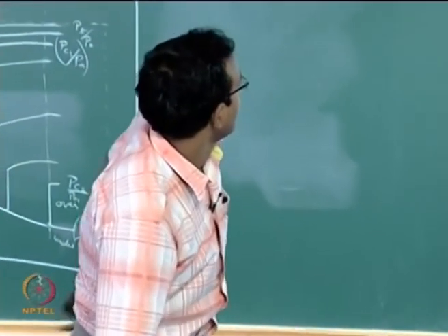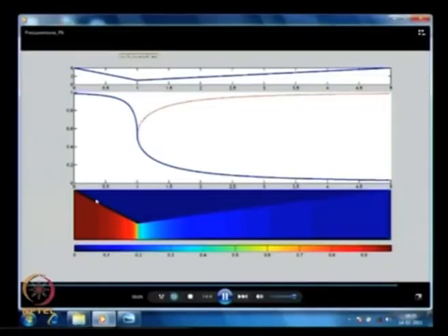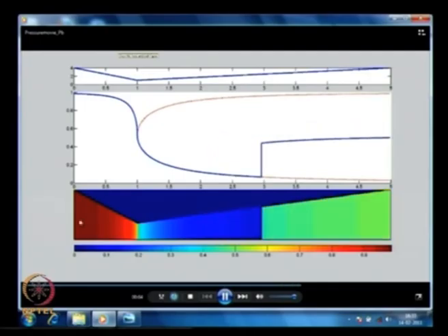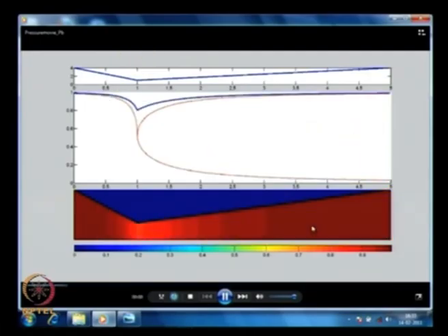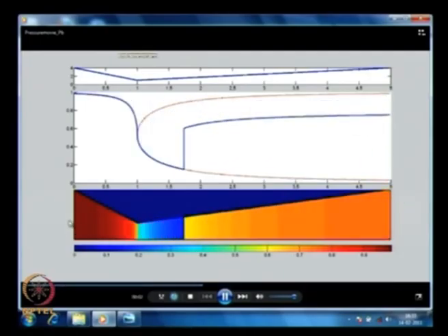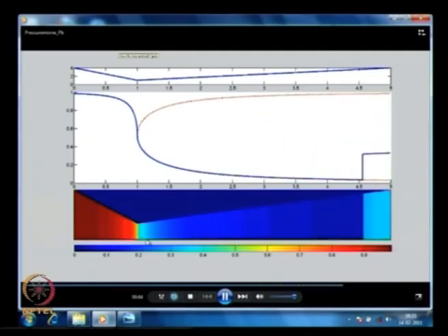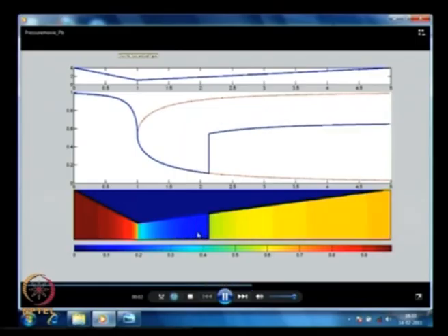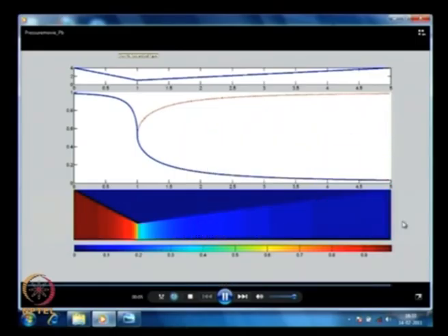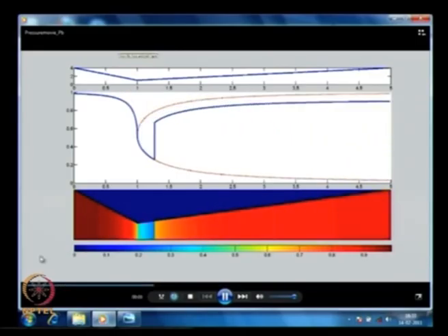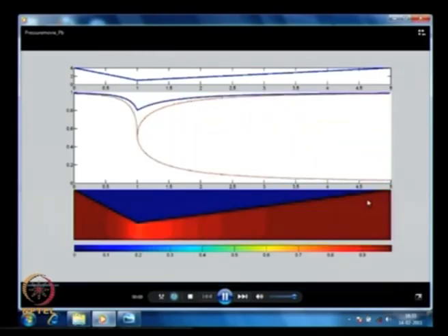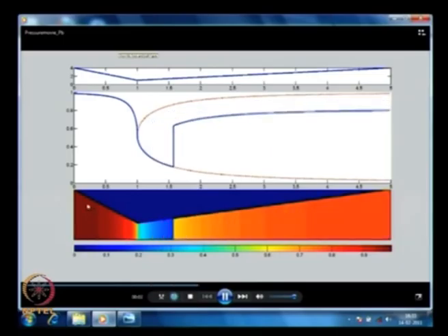This is the same thing, just I have added animation of pressure, color coded, red is high pressure, blue is very low pressure, and green is somewhere in the middle. So what you are seeing is very high pressure, coming to some green is your throat condition, choked, and then it is going subsonic and the shock is moving as we go. This is what really happens inside your nozzle. We saw a movie of this from an experiment, I think last class or the class before anyway.